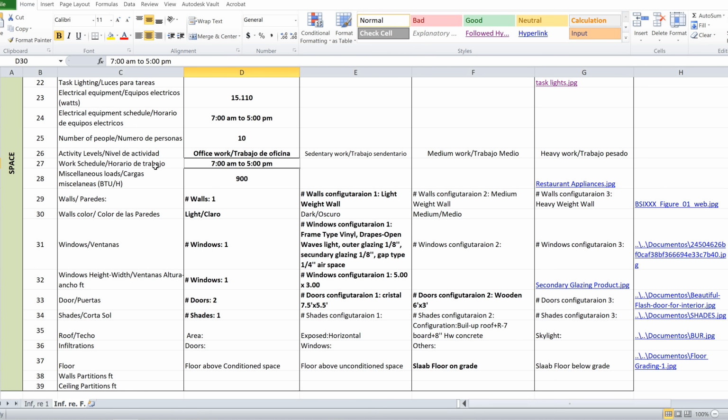For example, lighting affects directly the temperature of your space, and the sun radiation that heats your structure directly affects the temperature. But we also have to identify the latent heat. Latent heat is the one that affects directly the humidity of your space. So in order to select equipment that successfully handles the humidity created by different equipment, mostly this heat is created through vapor.